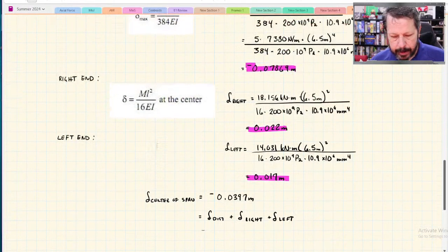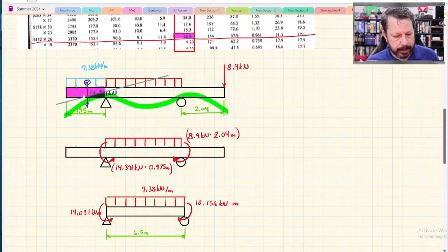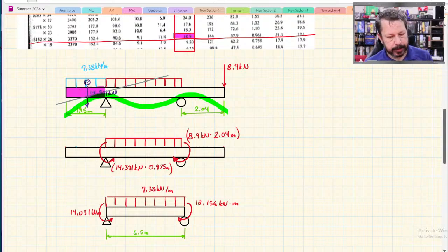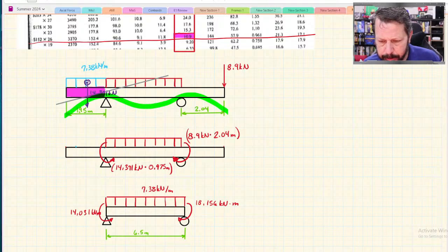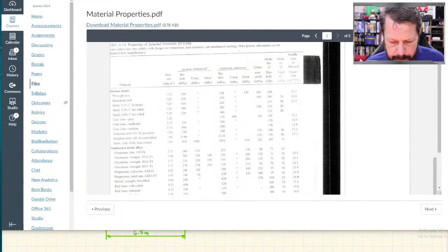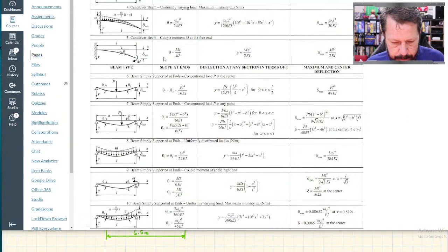All right. So the pink section here where I've got the blue distributed load, since that's a cantilever, the cantilever at its fixed support, which we're imagining the fixed support being the transition from pink to not pink, is zero slope. So well, let's look at the chart, make sure I'm right on how they've got our chart set up.